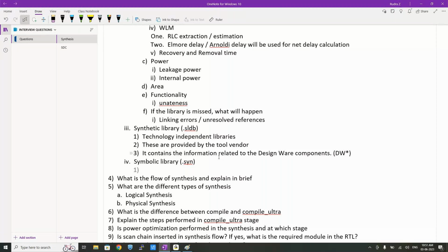Let's say for example I want a particular macro, and that macro is taking some time to develop. Let's say it needs a downtime of 2 months to get developed, and I don't want my project to be stopped. So what I will do here is find an equivalent macro which is globally used, and use the optimization methods. I'll take the help of the DesignWare components, and later I will swap those DesignWare components for the real macro once it is developed.